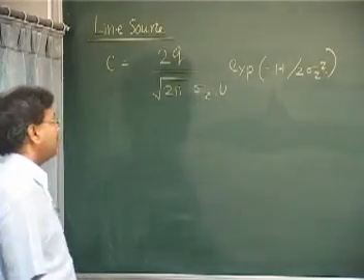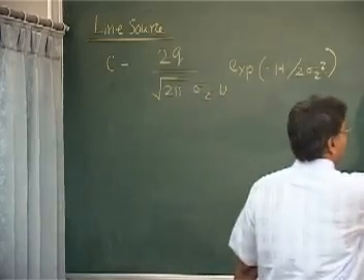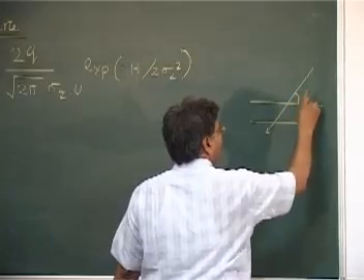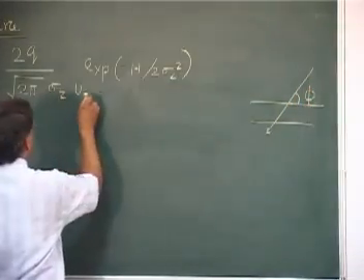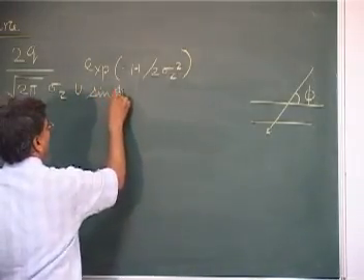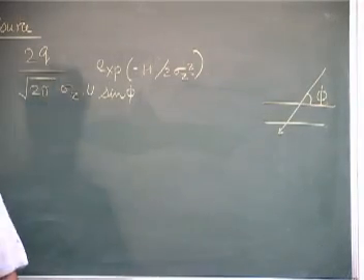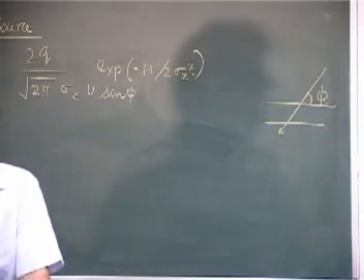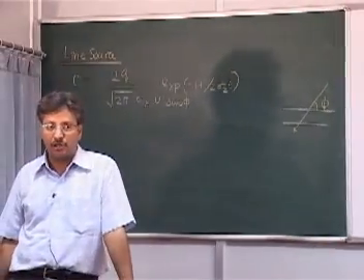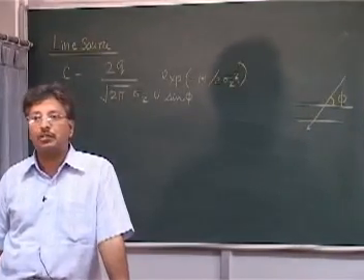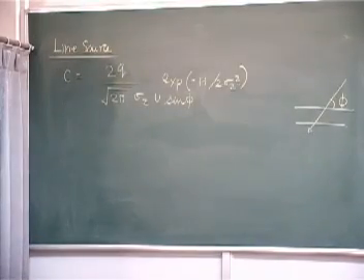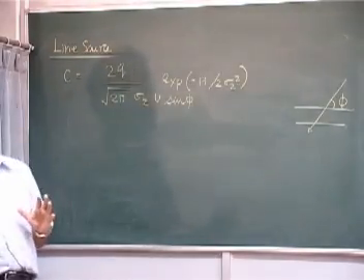All right. As was pointed out by one person later, suppose this is your road and this is your wind direction, making an angle phi. This sine phi should be in the denominator, okay. Probably we wrote it in the numerator, but it should be in the denominator for obvious reasons. If phi is 0, what is the concentration? It will almost be infinite. So you can't use this formulation if the angle is very, very small.